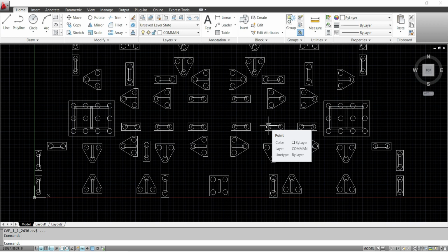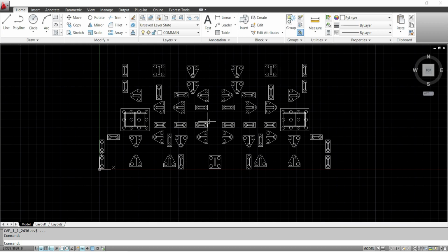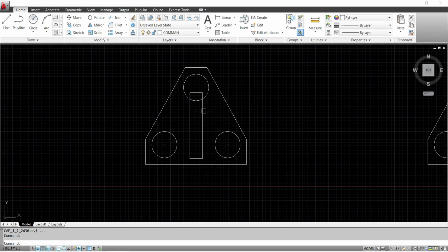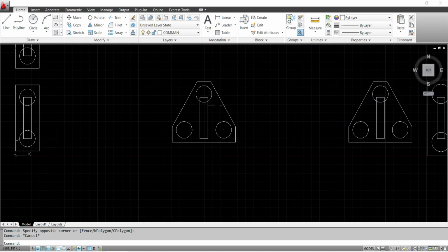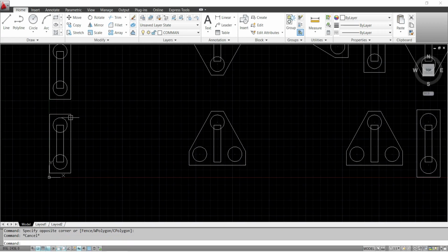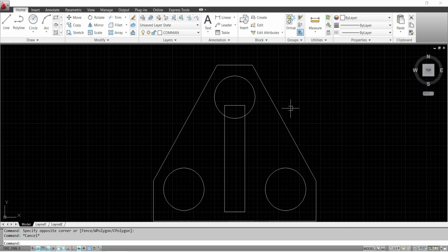What procedures are there? For the pile cap layout, you first need to fix, under which column and under which shear wall, how many piles are required, and on what criteria the number of piles will be decided. Thereafter, you need to decide the layout of your pile cap. This is a very interesting and very important thing, deciding the layout of the pile cap.